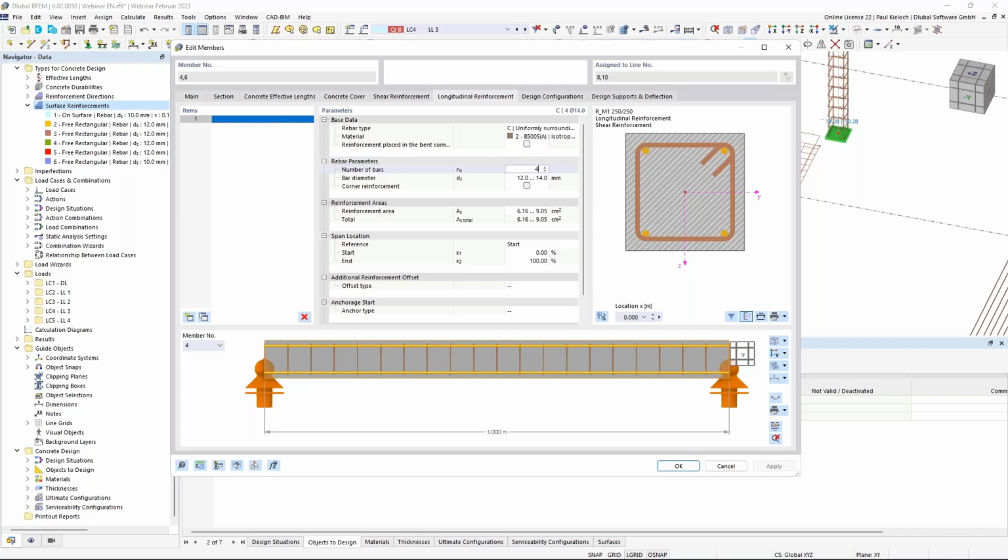So I would set it back to 4 rebars with 14 millimeters, and then it's the same for both, and I will get also the name or the description of the item back, because it's clear the amount of rebars and the diameter.